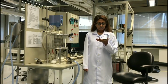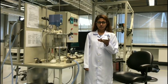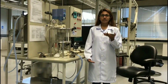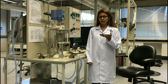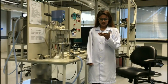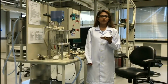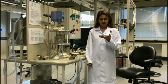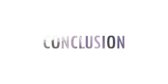The second error is that the rate of filling of the batch reactor with the solution at the beginning of the experiment was too slow. When the filling of solution is too slow, the reaction might have already started before we had the chance to start the timer. This causes inaccuracies in the results. The reason we did not use a pump for this is because the pump was functioning poorly. So the modification we need to do is to use properly maintained pumps to pump the solution from the feed tank into the batch reactors.